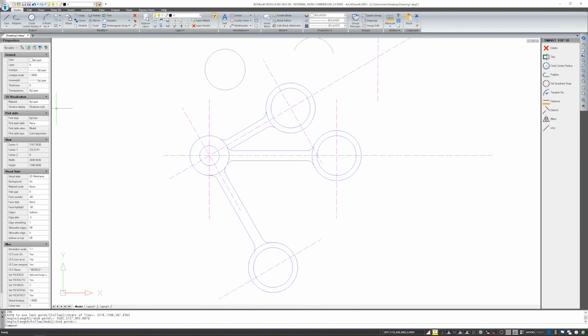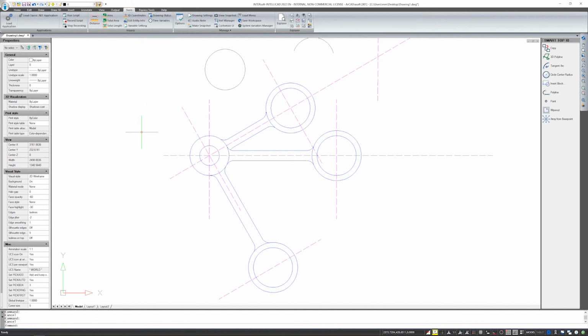Finally, I would like to show you one more element to be introduced. It will be on the home ribbon, here under the small triangle, and on the draw option. This is the point. This point on the screen, depending on what you need, can be a dot, a circle, a cross with a circle, any symbol that you will define for yourself, which can mark characteristic places, for example, on maps or in other documentation. You insert a point by selecting or by entering coordinates, depending on your need.